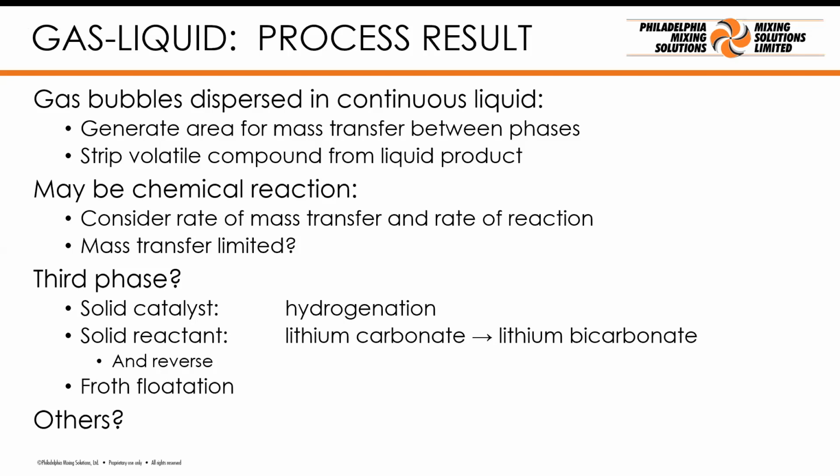But no, I completely understand you need your particles suspended, you need your gas dispersed, you need good contact between the particles and the bubbles so that they can adhere, attach, and then be lifted up to the froth at the top of the vessel. There are a number of things going on that we need when we think about our process result. What are all the things that we need to achieve? Gas dispersion, solid suspension, particles attaching to bubbles, bubbles rising to the surface without having the particles broken off.